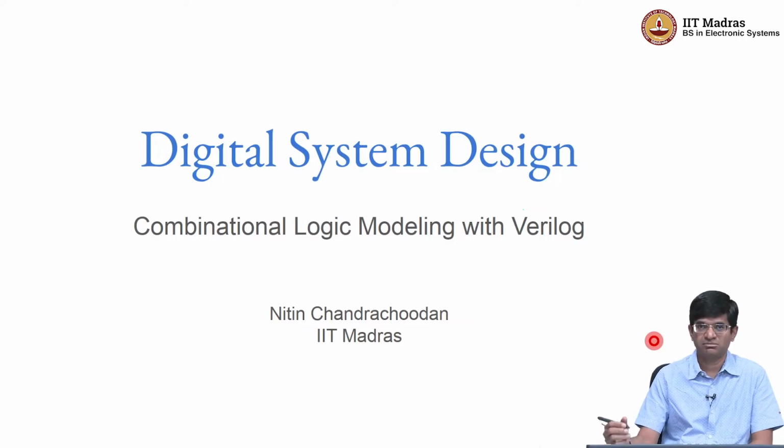For the most part, as a new learner to the language, you should probably focus more on SystemVerilog than on Verilog. Pretty much all simulators as well as synthesis tools have fairly good support for SystemVerilog at this point in time. So there's no real good reason to go with the older versions of Verilog as of now. And the additional features that SystemVerilog provides and also some of the safety capabilities make it worth the transition, if at all there is a transition that you need to observe at that point. Okay, with that in mind, let's get into the details of some of these lectures.